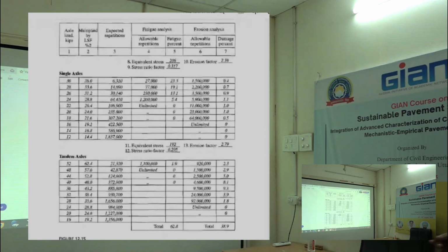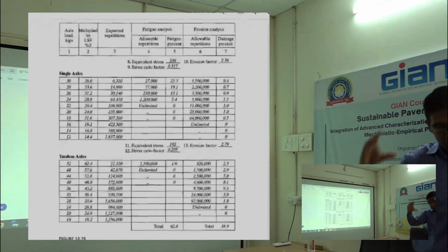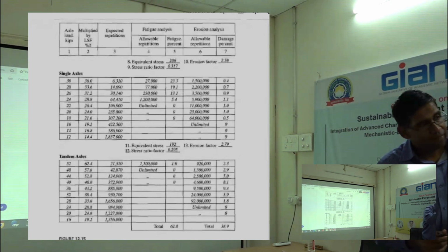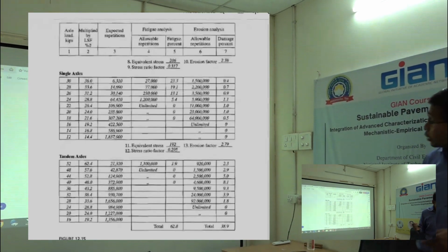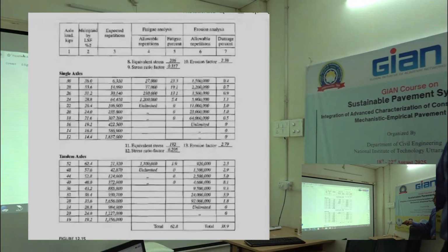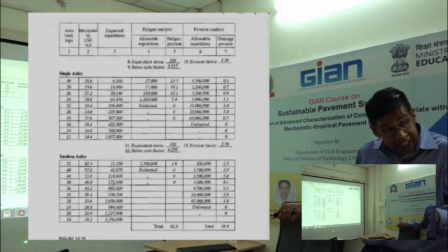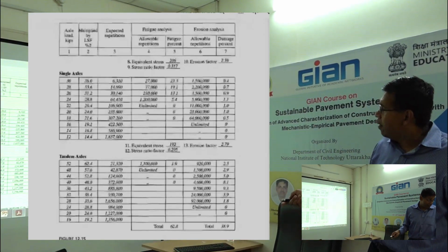Can everybody understand that? It's a trial and error process, because all my deflection, all my stresses depend on the thickness. So I need to get it. Summation of these two values or only one value? Each value. Yeah, if I add these two up, they are more than 100. Correct? So this would have failed. But this has passed. Each of them individually has to be less than 100.